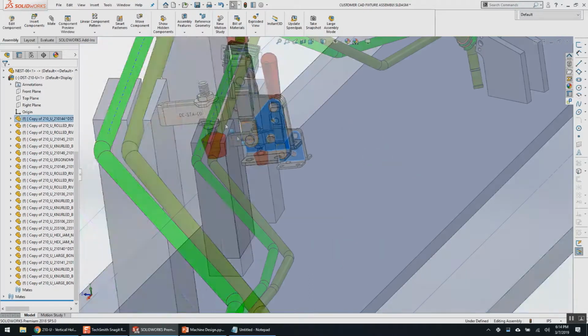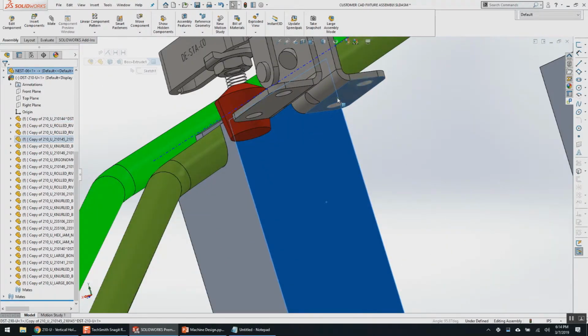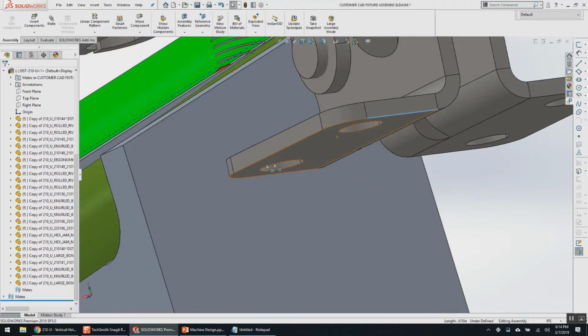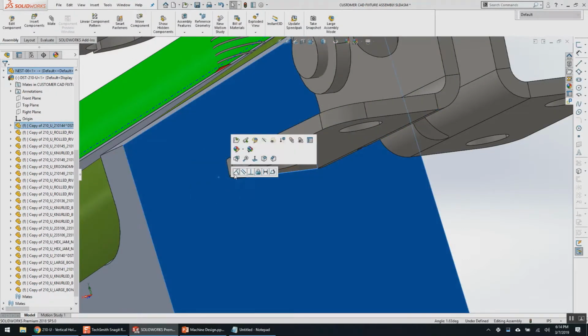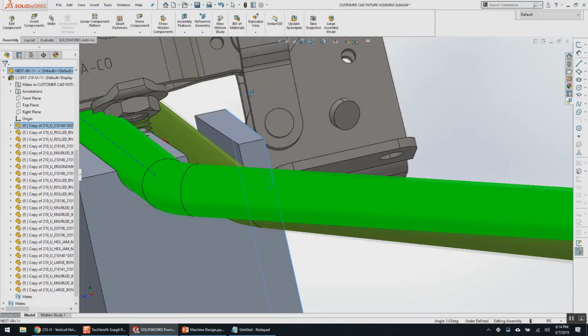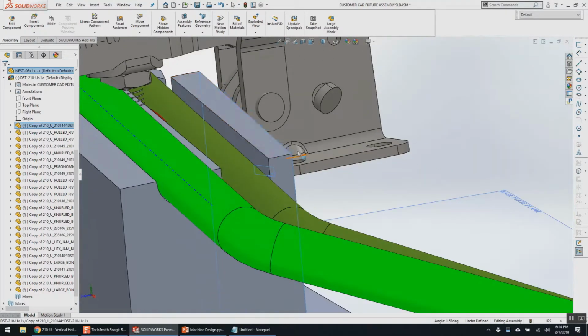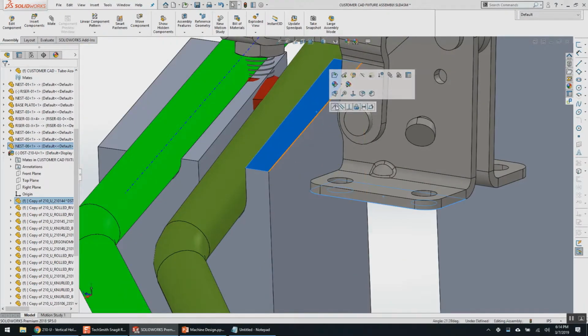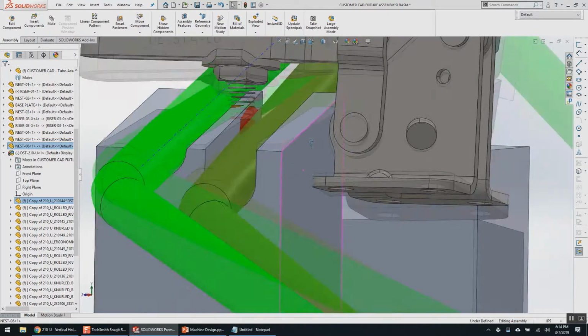All right, so let's move this around. Right click with the mouse and move will rotate a single object that's not fixed. Scroll click with the mouse will move your entire graphics pane. So let's say we want it to be right angle mated to that. Drag it away. Let's just pick an arbitrary dimension.